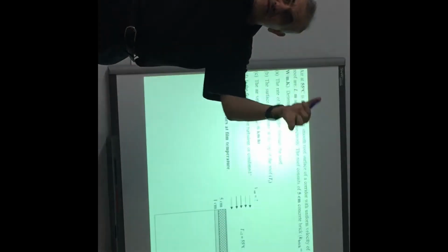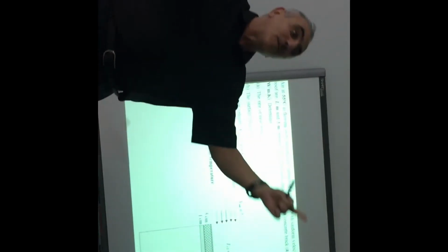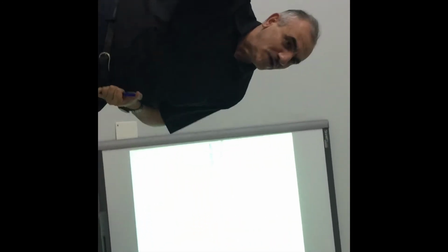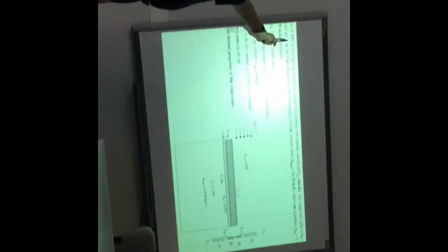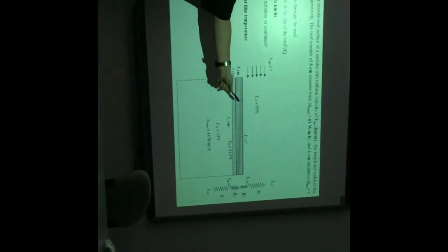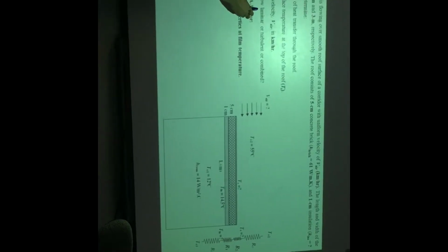You assume laminar, you determine the Reynolds number from the equation for laminar. After you calculate it, the Reynolds number shows the flow is combined. It means that in the first case, when you applied the Nusselt number, it was wrong, because your assumption was wrong. So you repeat the calculation of the Reynolds number. How do you repeat it? You go to the combined equation and apply the Nusselt number to calculate a new Reynolds number. That is your actual Reynolds number. Once you know the Reynolds number, you can find the velocity, because the Reynolds number is velocity times L over viscosity, you know that. And of course, you can answer right away part D, which is very easy.